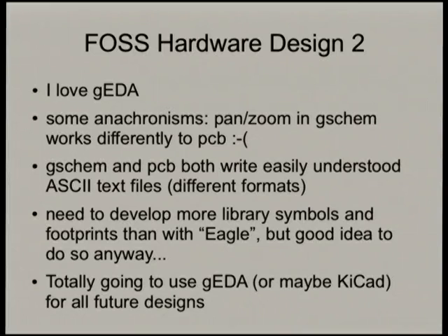In particular, the key combinations you use to do panning and zooming in the schematic capture program are quite different to the key combinations you need to do panning and zooming in the PCB program. So if you're switching back and forth, as you often do, you do a bit of layout and then realise you've got to change some pins in your schematic or whatever. You've got to keep switching your mindset from one set of key combinations to another, which is frustrating, but you get used to it.